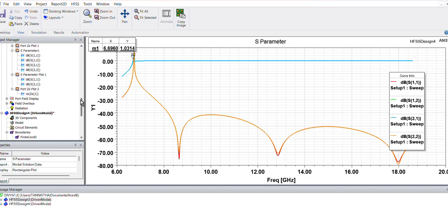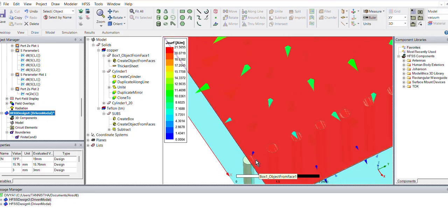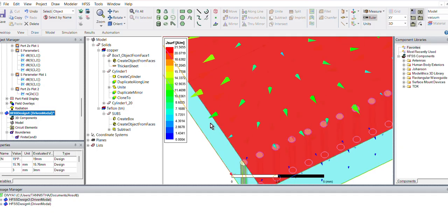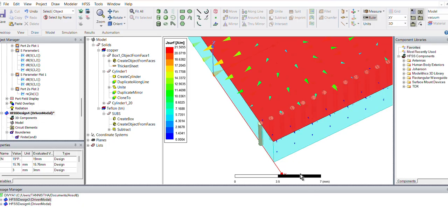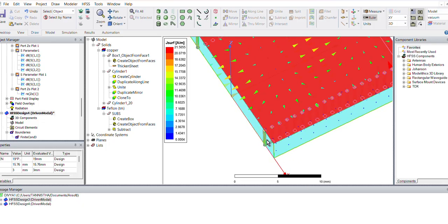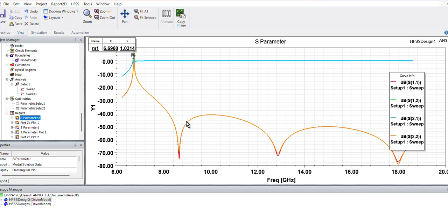So now we just have to adjust my A dimension to adjust my effective A dimension with the position of the PTHs, the x direction position of the waveguide, and by changing that we can again create the same structure. Here you can see we have been able to achieve 40 dB in the return loss.